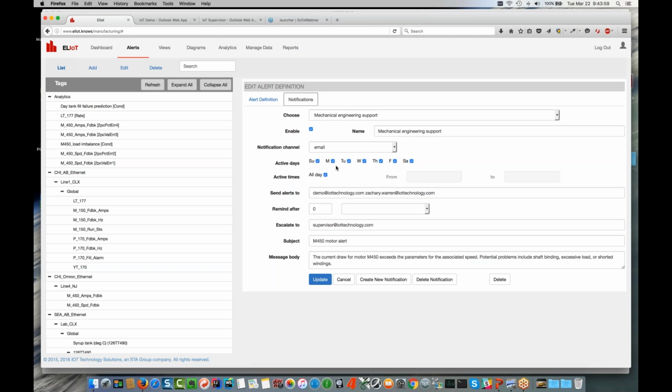We just wanted to point out that with these kind of analytics, so all the different things you saw, we can do things like measure material waste. For example, you can imagine out of your supply tank, integrating all of that flow, and then in your dispensing, your fillers, integrating those flows, subtracting those flows, and any difference is going to be wastage. We can also do things like chiller failures. We can understand the chiller failures by watching a moving average over time, or watching min-max. When chillers start to fail, sometimes the compressor stays on all the time, and you see that instead of a little bit of a sine wave or a sawtooth, the temperature inside the refrigerator stays constant.